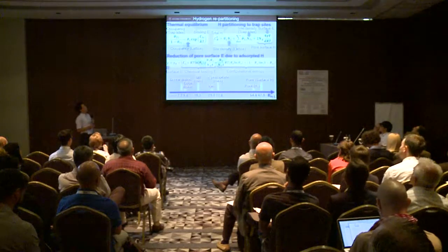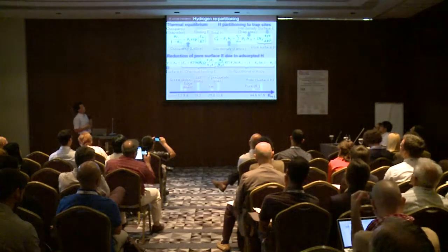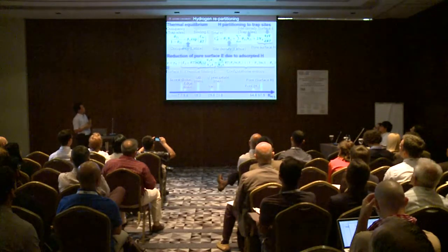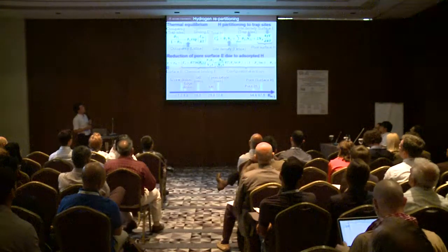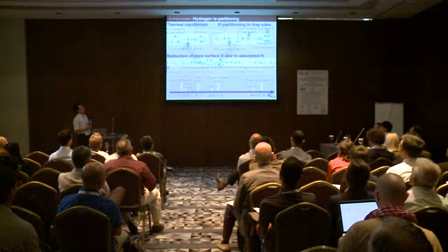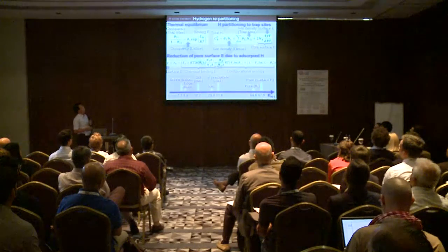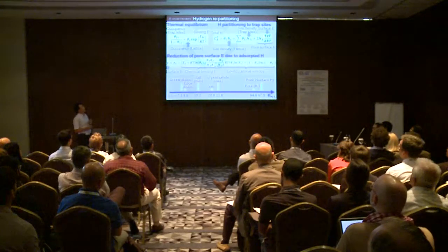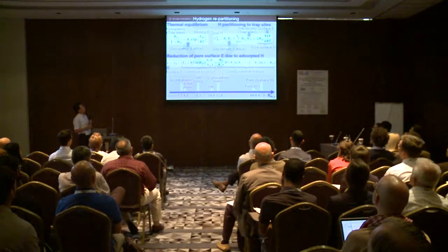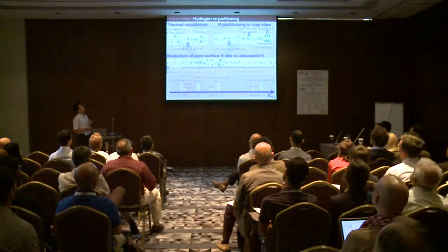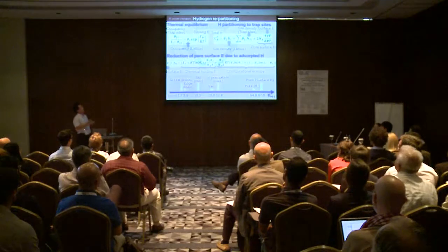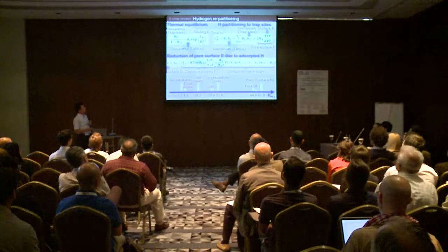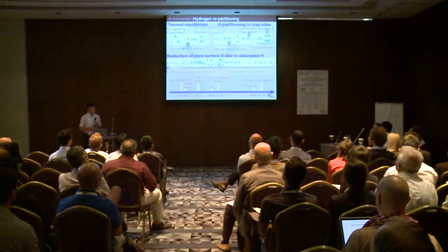So fundamentally, we do the analysis by using these 3 equations. One is thermal equilibrium among various trap sites. Another is that total hydrogen is partitioned to the lattice interstices and various trap sites, including micropores and nanovoids. And also, the surface energy of a pore is reduced due to the existence of adsorbed hydrogen onto the aluminum surface. And we fundamentally solve these equations utilizing these trapping binding energy data.